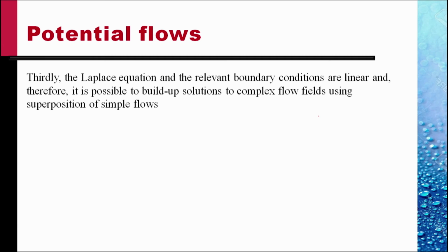The third important property of the potential flow is that the Laplace equation and the relevant boundary conditions are linear, and therefore it is possible to build up solutions to complex flow fields using superposition of simple flows.